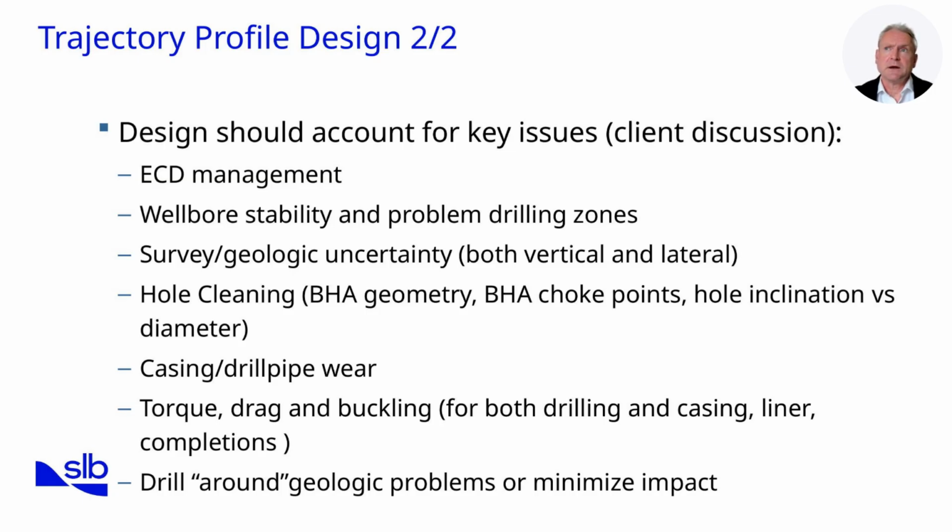Casing and drill pipe wear must be considered, especially across doglegs or long tangents. Finally, the design must address torque and drag and buckling, not just for drilling, but also for running casing, liners, and completions. In some cases, it is better to drill around geologic problems rather than directly through them. This flexibility can prevent instability and reduce risk. Next, we'll turn to surveying and geological uncertainty, another factor where ERD wells differ significantly from conventional design.